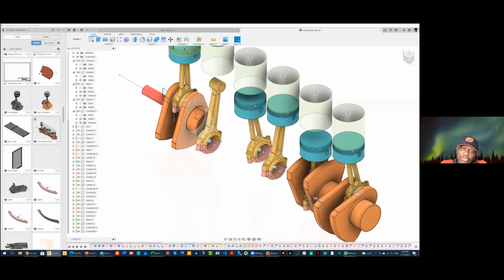All you need to do is take a plane here, create a sketch and extrude it, and then after you have extruded it, you can cut it and create two components, up and down, so that otherwise there will be no way of putting this inside the crankshaft. That is the only difference between this and what we did before.